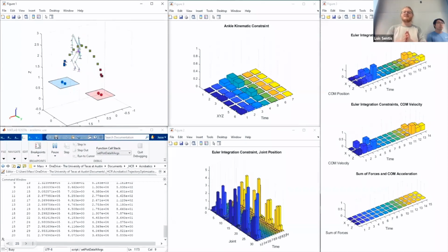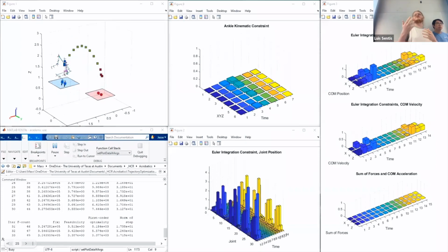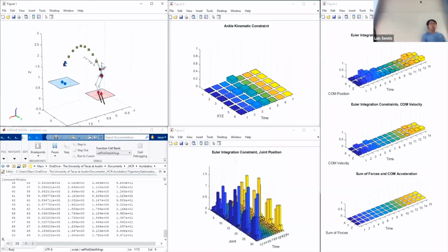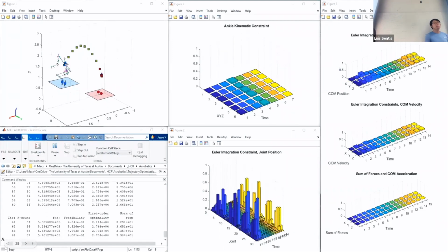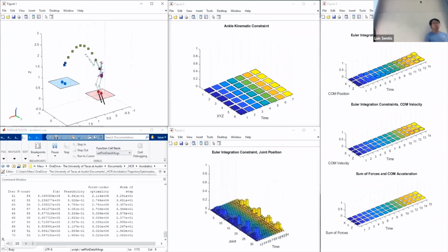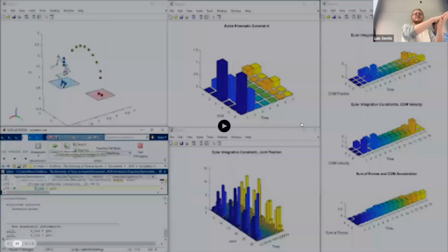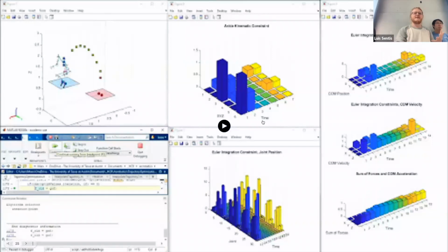And the thing I'm really excited about, because I haven't seen this anywhere else, is that we said the constraints are not always feasible and not always satisfied. This is actually plotting some of those constraints, where you can plot the knot points over time and what the variable is. And you can see that in these high blue spots, our Euler integration doesn't work. Our velocity and our position are not agreeing. And as this runs over time, it shrinks down, which shows you that it's getting better.